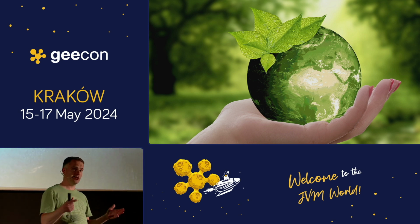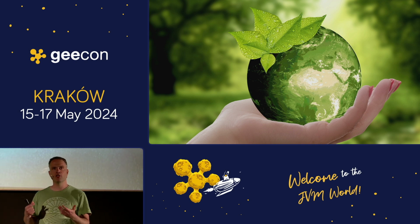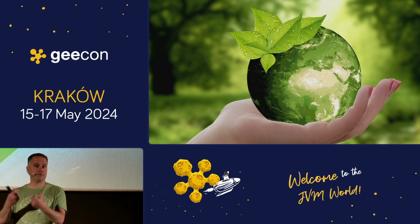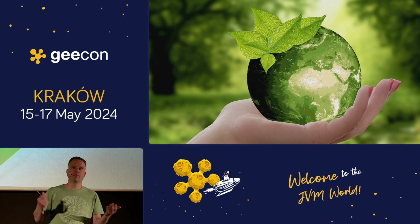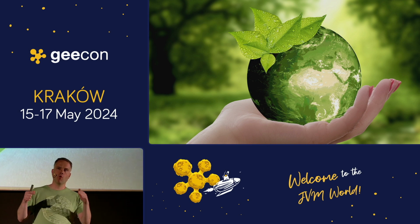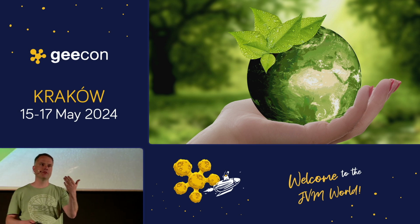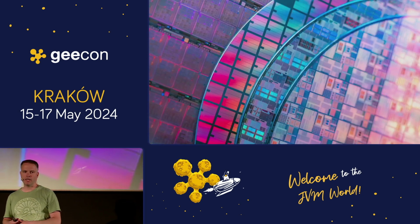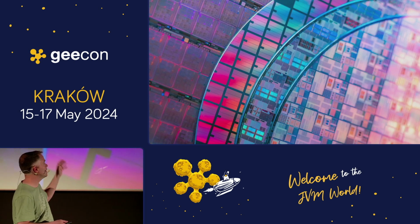And it's even more complex. If you have an advanced chip, let's say the latest you have in your laptop, some of the layers are critical. There you want really small functionality, small transistors. But for the connecting layers, you don't need that amount of detail. So for one chip, you could use a really advanced EUV machine for one layer, and for the connecting layer, just use an old DUV machine. So you can mix and match those approaches. And then you get chips like this. These are real-looking chips, in various shapes and forms.